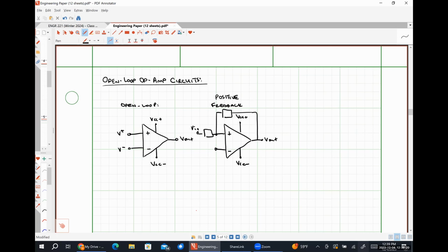Where we're going to apply an input voltage. It technically could be, let me just put Vn plus here and Vn minus here. So we might apply our input voltage at the left-hand leg of that generic circuit element. But the main part of positive feedback is that we have a feedback path from the output of our amplifier back to the non-inverting input terminal.